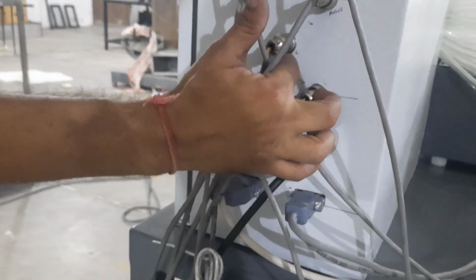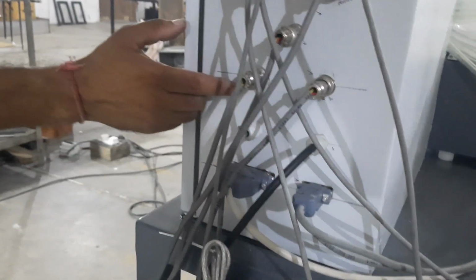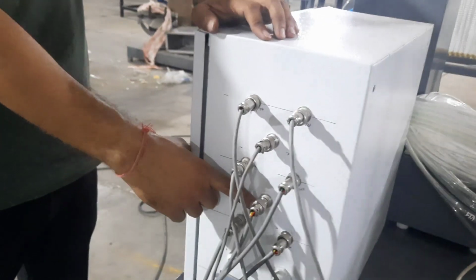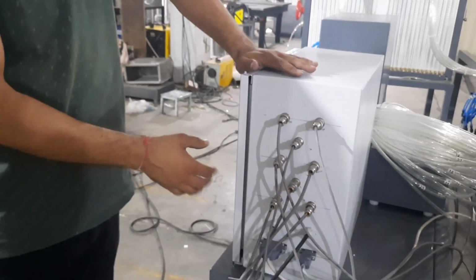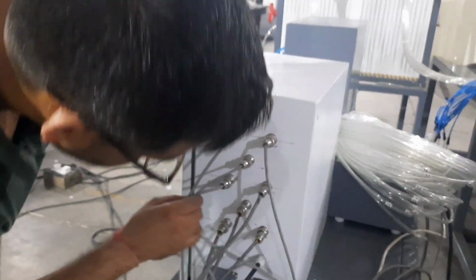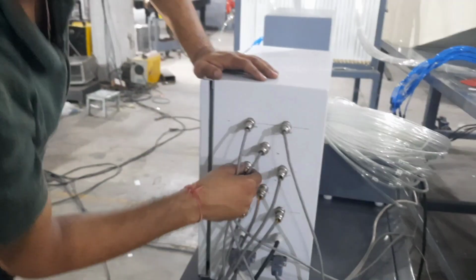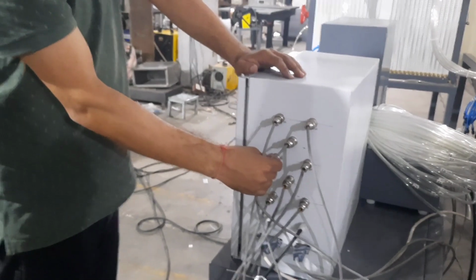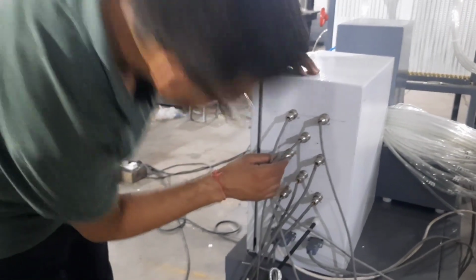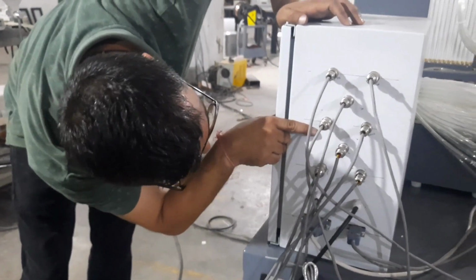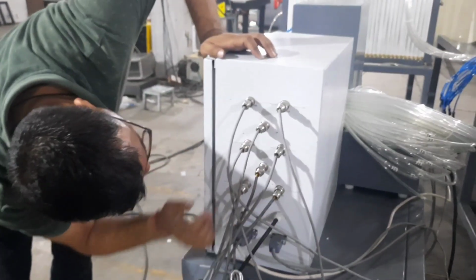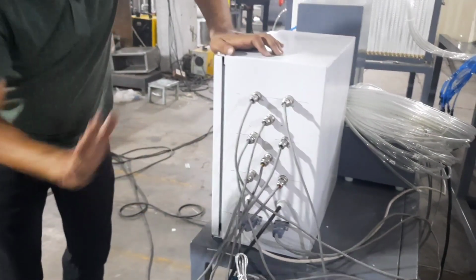And these three are the connectors which give you the readings of the load cell in the X direction, Z direction and Y direction. X direction denotes the drag force, Y direction denotes the lift force, and Z direction denotes the pitching. And this one is for the LVDT as indicated here. This one is for the angle, and this one.